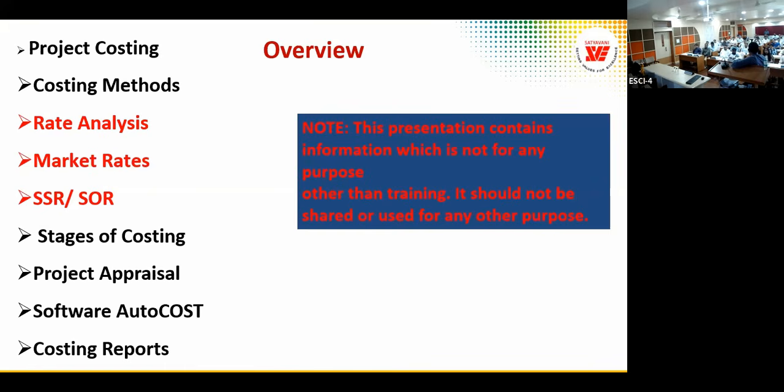But we have the thumb rule or plinth area rates. CPWD has given certain plinth area rates. Normally, if it is an RCC building, as per CPWD we have 4,000 rupees per square feet as the cost of construction of the building, including E&M and finishes, and then we have to add external works. Other than the building, externally we have electrical, drainage, plumbing, STP, and boundary wall.